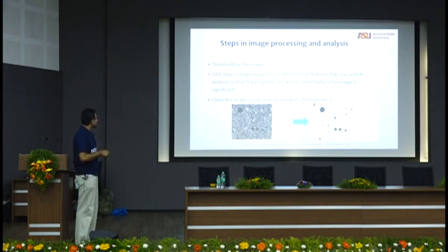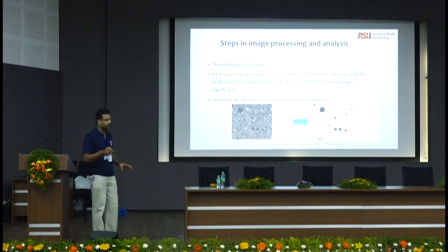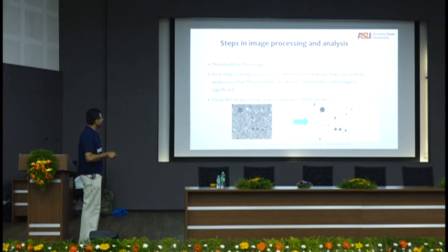So here's an image, and I have thresholded it just by setting a grayscale of close to 0, maybe 0 to 10, 15 maybe. Again, you have to play around to find out what value you would want. And once I threshold it, what do I have now? Pores and everything else. Pores and solids, right? The white is a solid, black is a pore.